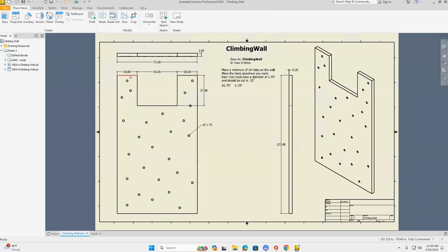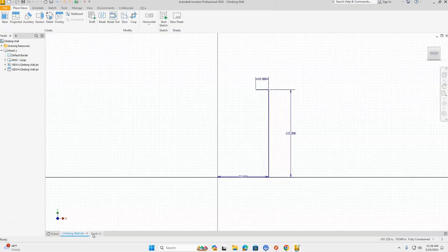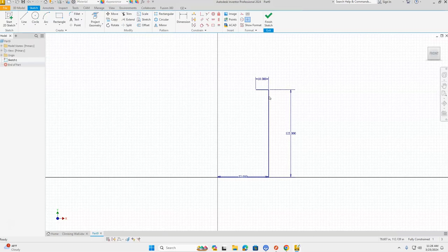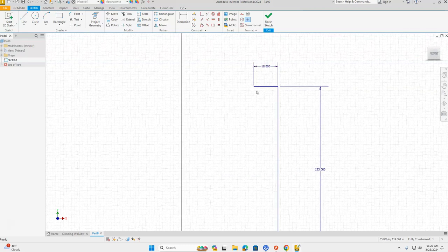And then we're going to go across the top to the left, and this line here is 18 inches. Once we get to this point here, it's going to be an easy task of just creating an end and boxing this in. We're going to go from here all the way back down to the origin, get a green dot, and close this shape off. Okay, let's take a look at how to do that on our computer. Once again, this is where we left off at the top.